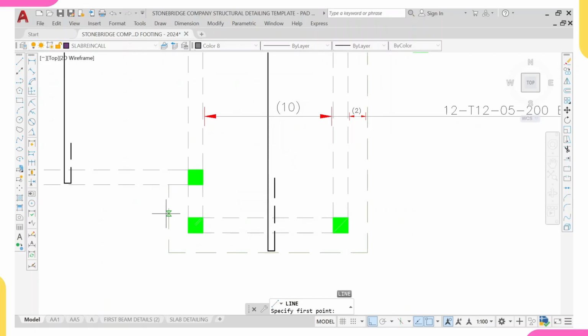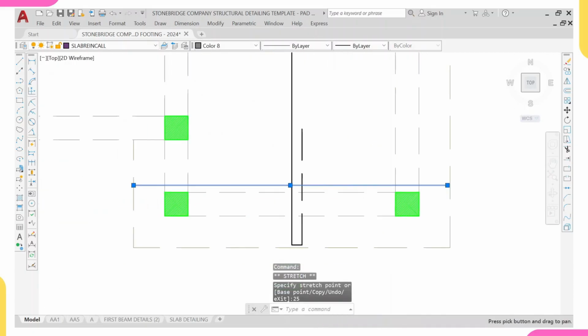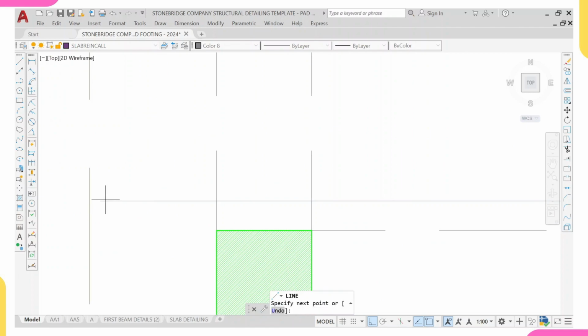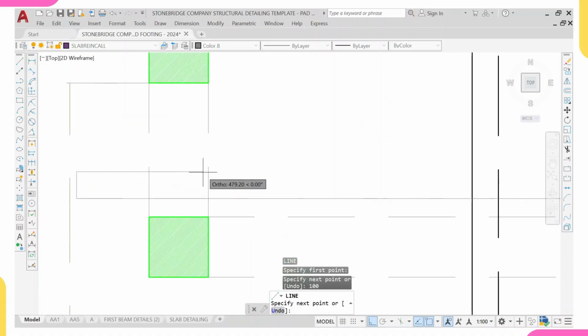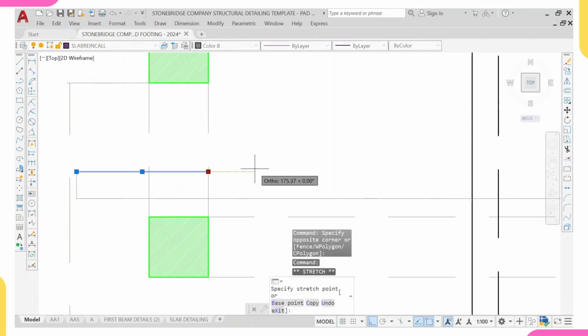Let me detail this one. This one will run from this point to this point. So I'll click on it, then input my concrete cover of 25, enter. I'll also come over to this point, then input my concrete cover of 25, enter. Escape, L, enter. Remember our sidebar, sorry, I made a mistake, L, enter. Our sidebar should be 100, enter. Then I'll place it at this point. Then I'll input my wrapping length, which is the center and top reinforcement, which should be 600, and click enter.